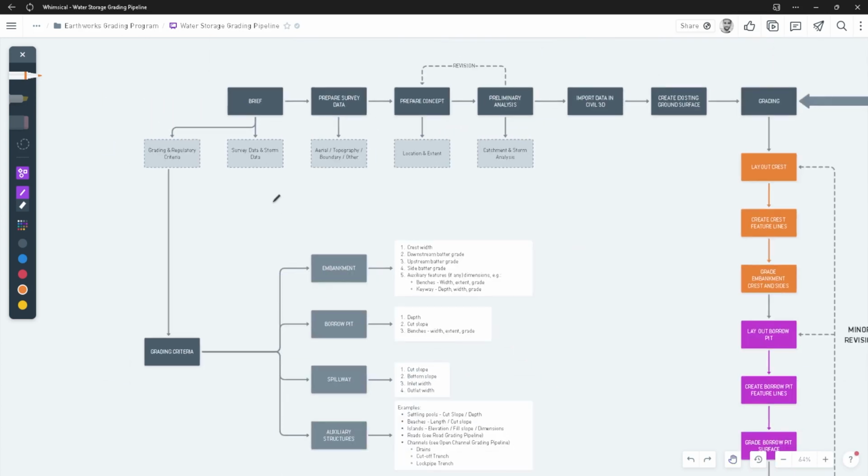So nowadays a practice is to slightly oversize things, because usually we cannot easily find more than the 100-year flood data. So unfortunately we kind of are in the blind, so we have to oversize structures like spillways, to be able to have some buffer against events larger than what has been recorded.